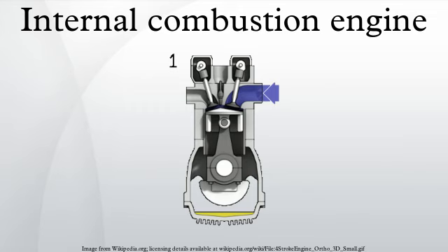Gas turbines. A gas turbine is called a gas turbine because it compresses a gas, usually air. There are 3 stages to a turbine: 1, air is drawn into a compressor, 2, fuel is added to compressed air and heated in the combustor, and 3, hot air is released through the turbine's blades which rotate a shaft connected to a generator.